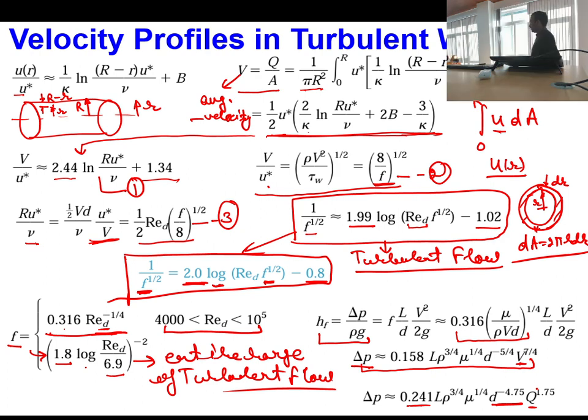It means that if we have a pipe and in that pipe I have some Q amount of flow rate, for the same amount of flow rate, if I increase the diameter of the pipe, under the laminar flow conditions, my reduction in pressure drop will be less, but in turbulent flow conditions, by increasing the diameter of the pipe, reduction in pressure will be more.